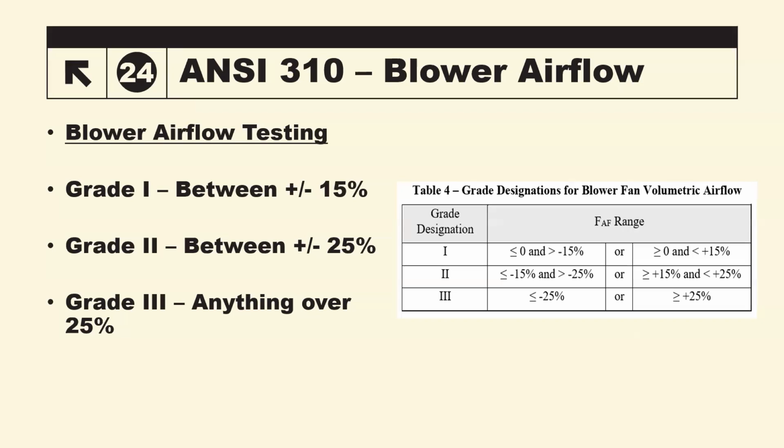To go down that rabbit hole, this is where we talk about the previous webinar we had and webinars before this, which is proper duct installation. If you've got kinks, sharp bends, crushes, compromising of ductwork, the system's trying to pull in as much as it's pushing out.